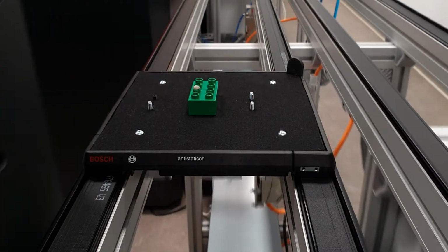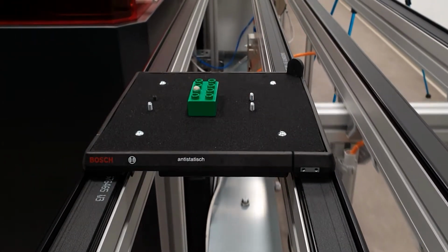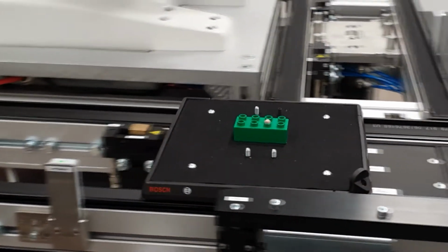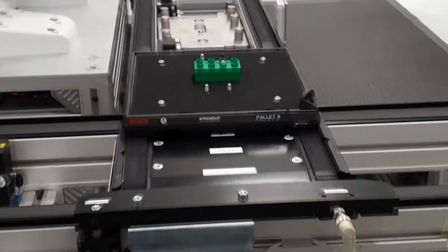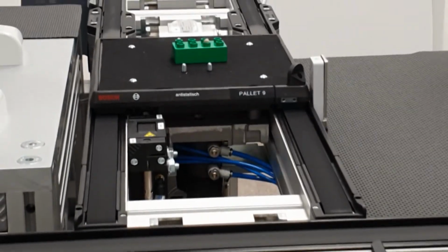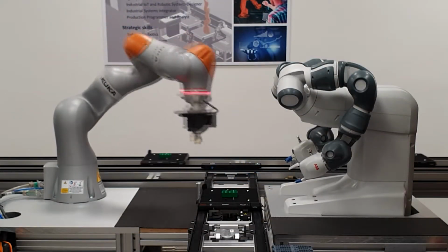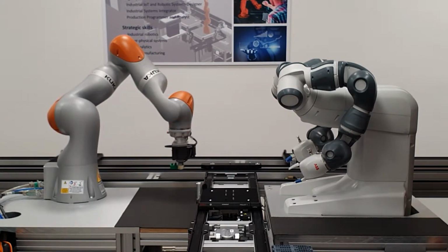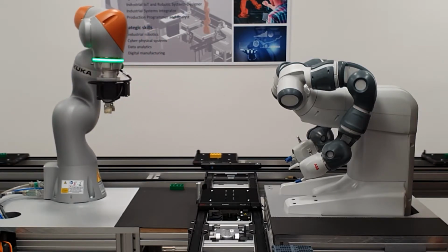The line transports many pallets, directing them to the different areas. The line software, handled by a Siemens PLC, is programmed to be reconfigurable and permits moving and tracking every pallet without a predefined path. The line is controllable remotely thanks to the OPC UA protocol or with the operator panel. The assembly area will take 2 pieces to put them in one monopallet.